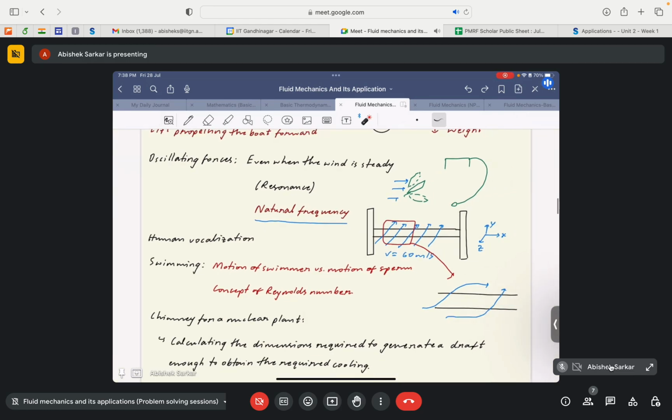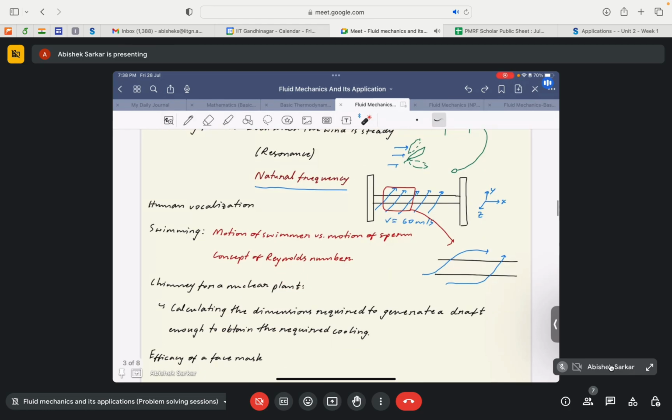As Professor Gupta again pointed out, to rectify it, after the failure of the initial bridge, the engineers tried to create a bridge that was much stiffer than the initial design. They might have reinforced the deck in every span, like this is the span of the deck, in certain areas, so that the stiffness of the deck increases, and thus the natural frequency goes up. I guess that was the way by which the engineers handled this critical problem.